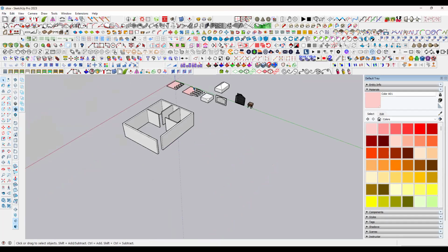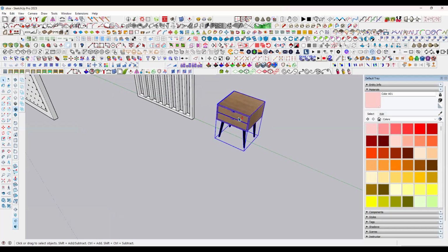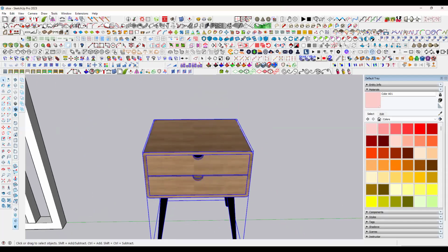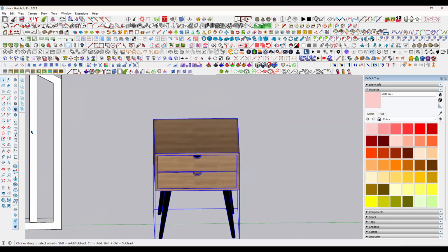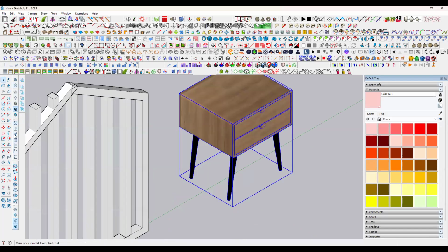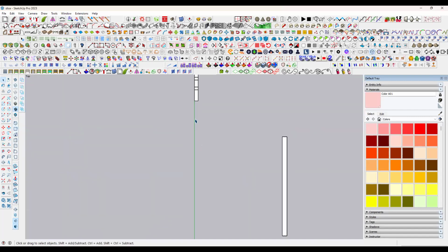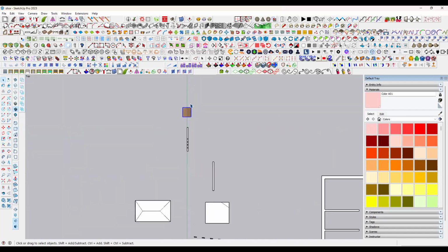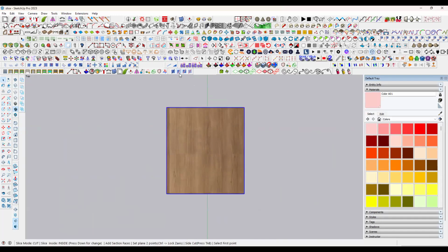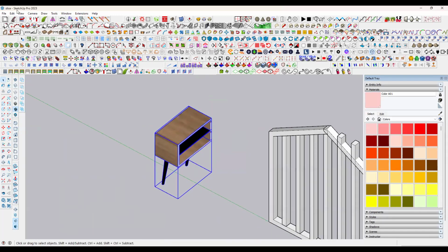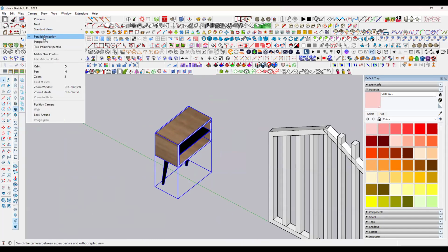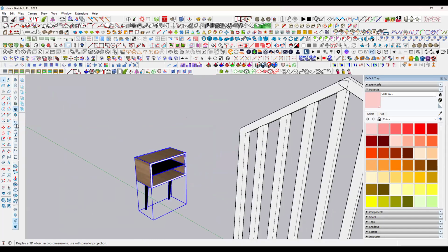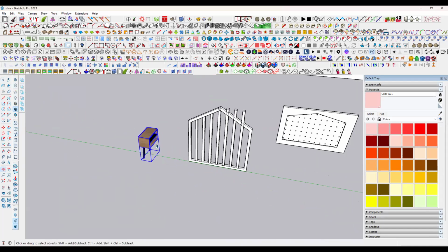So then maybe this whole model also, if you want to make it a slice, we can easily make it a slice. Say I'm going to the parallel view, go to the top view. Generally, if you do a normal slice, the system is going to hang. But with the help of this one, see, I'm going to take exactly the center. Now I'm going to slice this one. See, if you use this plugin, the system won't hang. So that is the advantage.